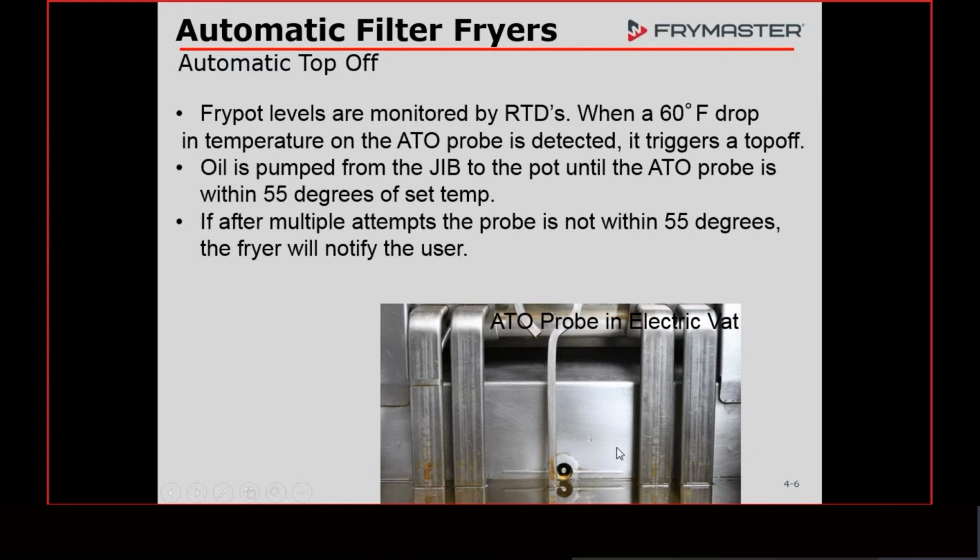All right, some of the things that I've found have been a little bit misleading. Well, one, let's go back up just one. On the system, when it first comes on, the pump will come on for 1 minute, and again, what it's trying to do is get that oil level to that probe, okay. If it comes on for 1 minute and we do not see the rise in temperature on that probe, it's going to stop. It sits there for a minute, and then it's going to come back on for another minute, okay?